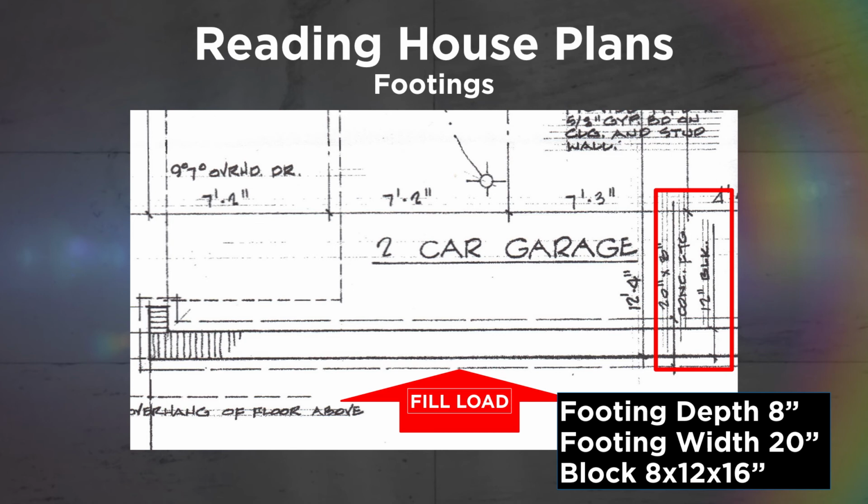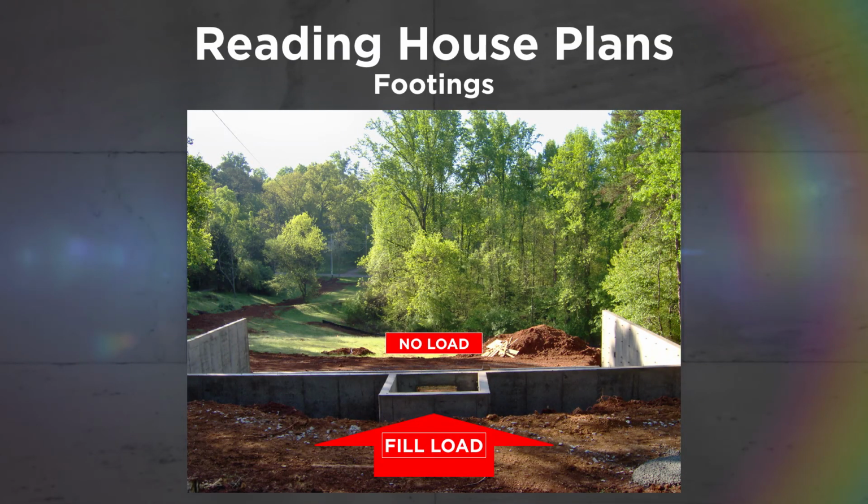In the red box, notice that the footing is now 20 inches wide instead of 16 at the rear, and the block is 12-inch block as opposed to the 8-inch block in the rear. This is a good example of a home that will be open on the rear of the basement level, similar to our house plan. Instead of block at the rear of this home, an exterior stud wall will be added. The field dirt will then be pushed tight against the wall when the home is complete.